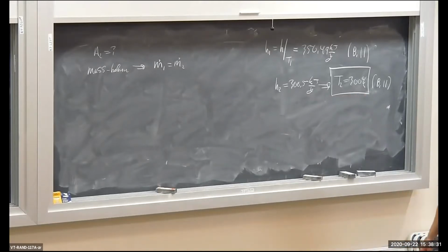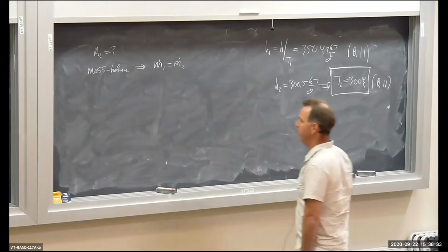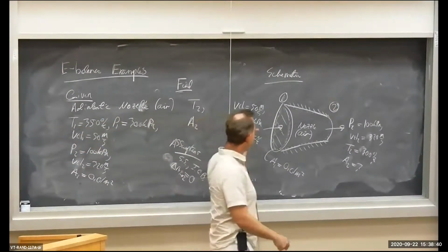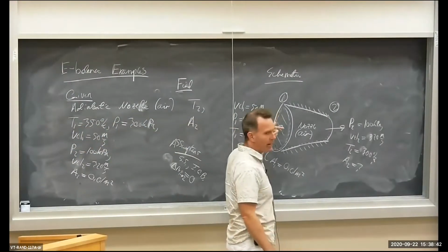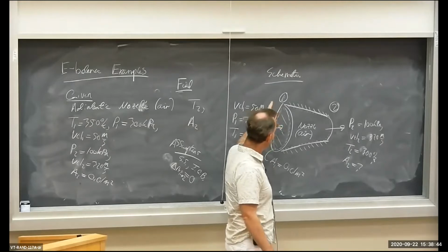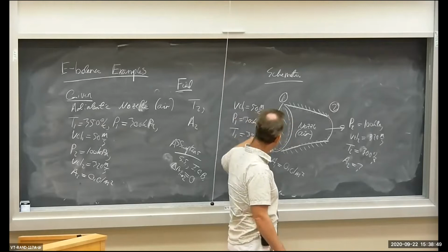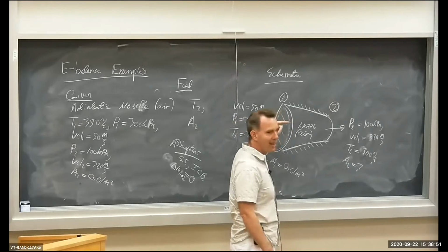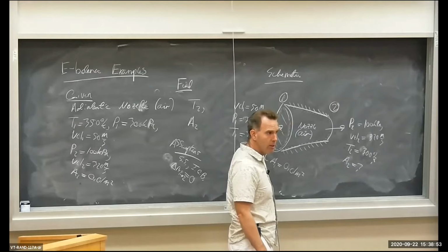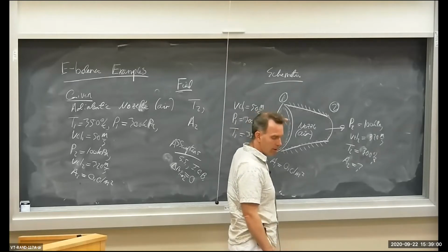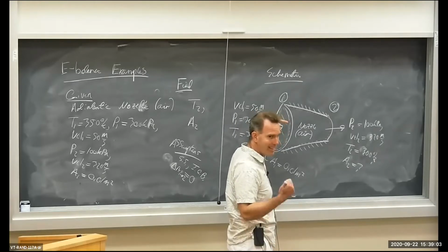Now, what's the mass flow rate at the inlet and the outlet? The mass flow rate at the inlet is equal to the density of the air at the inlet times the flow area times the velocity. Velocity in meters per second times an area gives cubic meters per second, a volume flow rate, and you go from a volume flow rate to a mass flow rate with density.